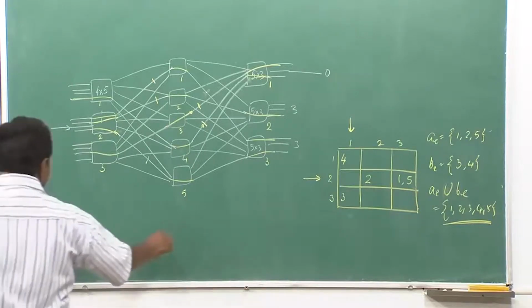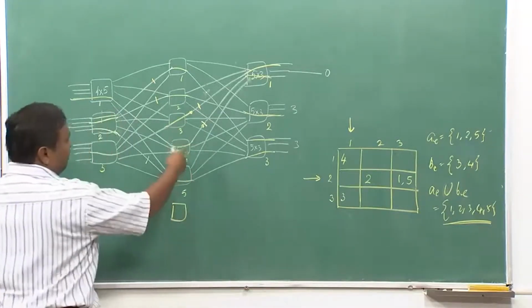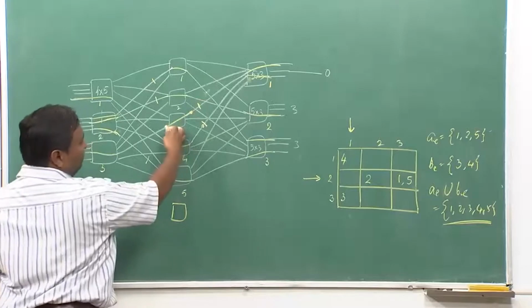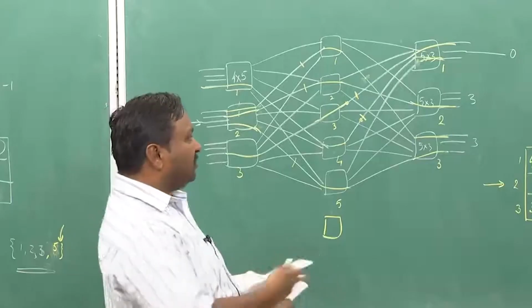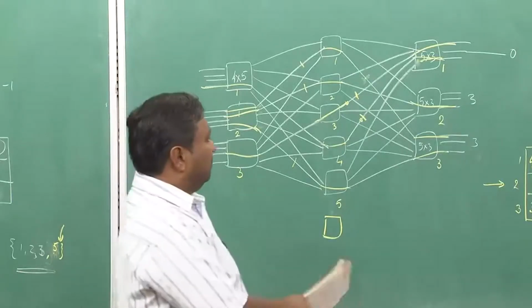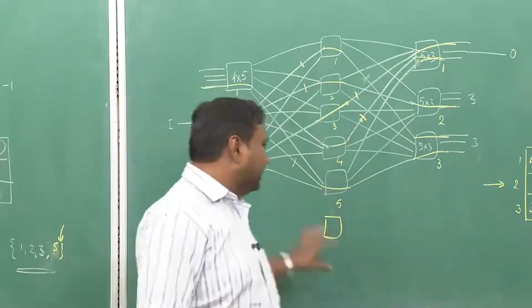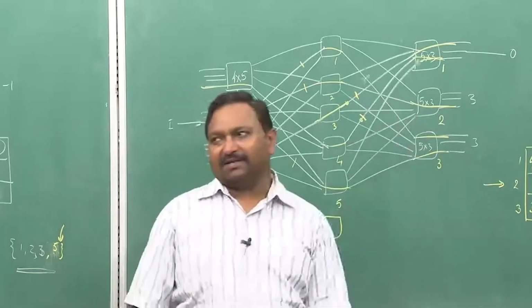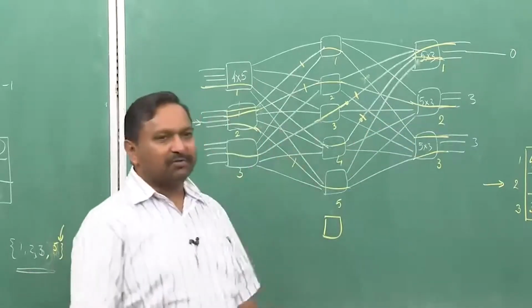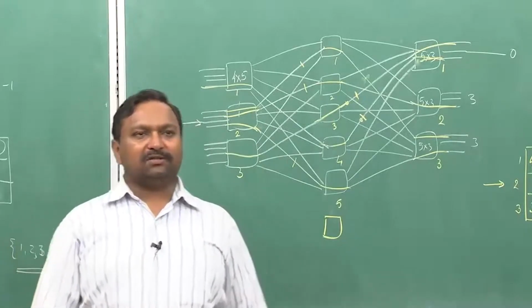The moment I add one more, a 6th, and this is a worst case scenario. So, remember these 2 are connecting to these switches, these 3 are connecting to a different one, and their sum total is equal to the total number of middle stage switches. I created one extra which is free. Now, this can always be used to set up the path, and when I make it equal to 6, this satisfies the Clos condition.